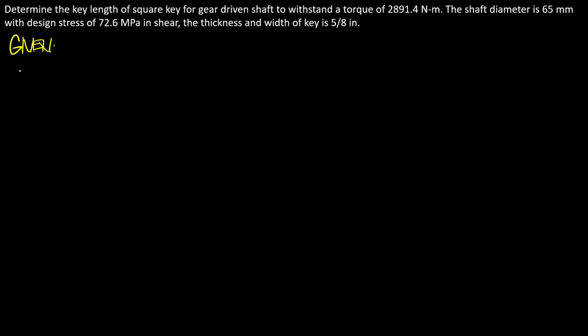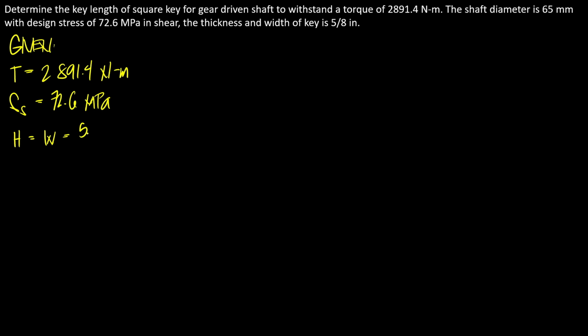Given torque is 2,891.4 Newton meter, and the design stress in shear, or shearing stress, of 72.6 megapascals. Okay. And the height and width of the key is 5/8 inches. So we need to find its length.